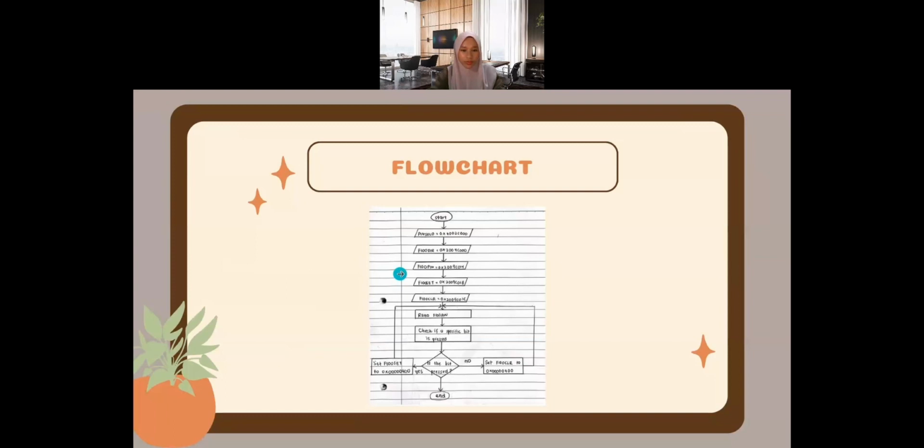After we identify all the inputs, we are going to read FIO0PIN and check if the specific bit is pressed. If the bit is pressed, we are going to set FIO0SET to 0x00000400, and read FIO0PIN again. Then if the bit is not pressed, we are going to set FIO0CLR to 0x00000400. After we set FIO0CLR, we read FIO0PIN again. This means our coding is not going to end. It's never ending.